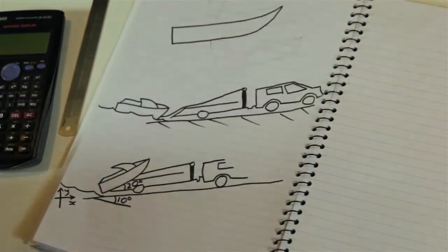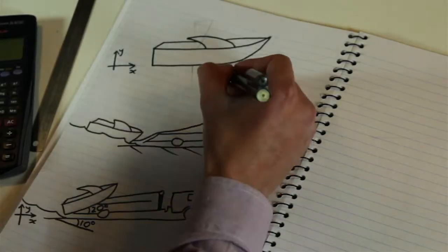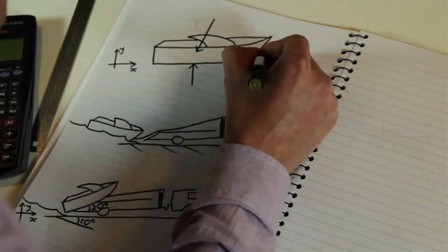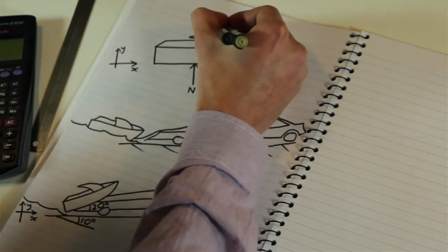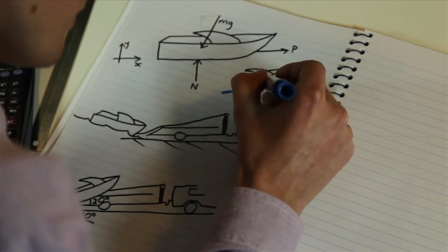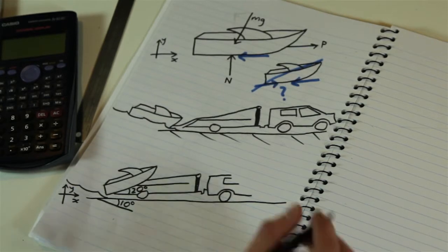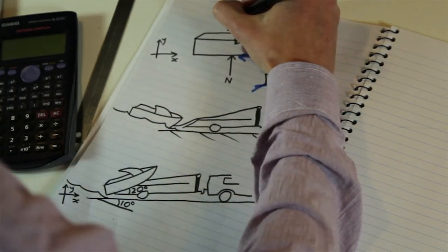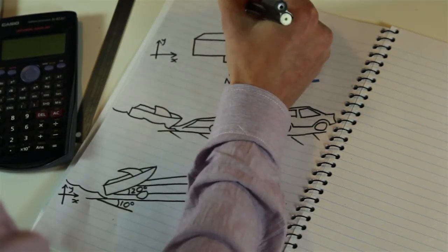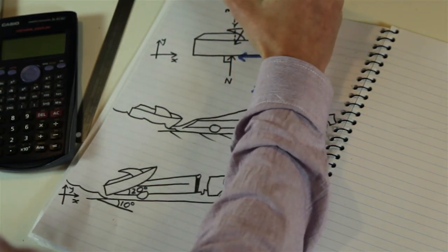Now we draw a free body diagram of the boat, showing it isolated from its surroundings, representing each force acting on the boat with a vector arrow. We know that friction acts tangentially to the surfaces in contact, but is the friction force acting up or down the ramp? We expect the boat to move up the ramp as the winch pulls, so we'll assume that friction acts down the ramp. Note that we haven't considered the size of the area of contact. This is because the magnitude of the friction force is independent of the area of contact, as long as neither surface dents the other.